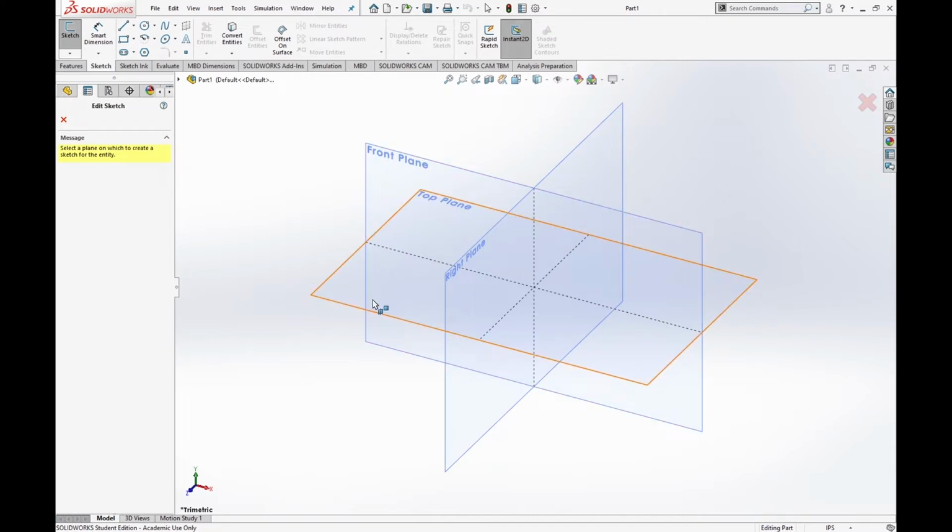It's important to a certain extent what plane you start on, because eventually we're going to bring this gearbox into the CAD model of the car. Depending on how you orient the gearbox at this point, sometimes you want to make certain planes, and it's good to maybe orient your gearbox in the correct plane. That's up to you, however you want to do it. You can always create reference planes down the road if you need to mate to a plane.